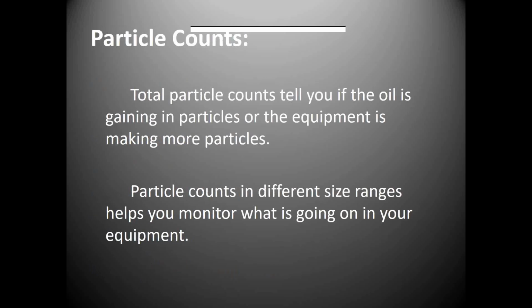So our total particle counts. We talked about this in the last couple sessions here. As the particles go up, we're getting more wear. And these particles can be in different sizes. So oil analysis is going to tell us how many of those particles are of those different sizes.